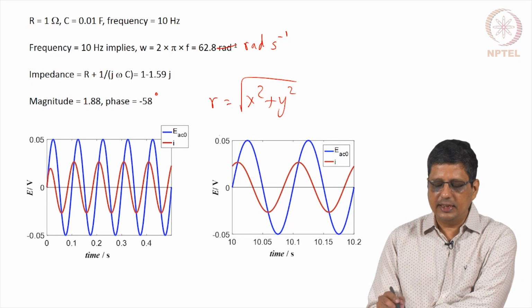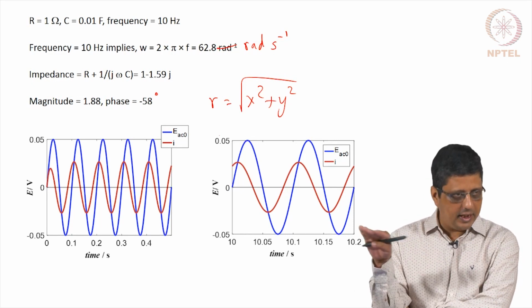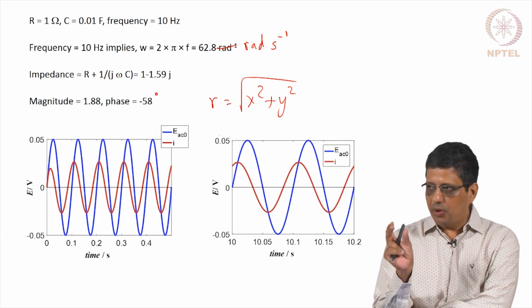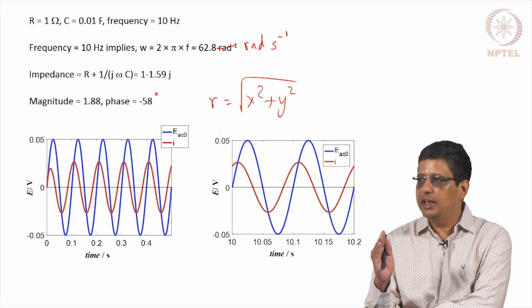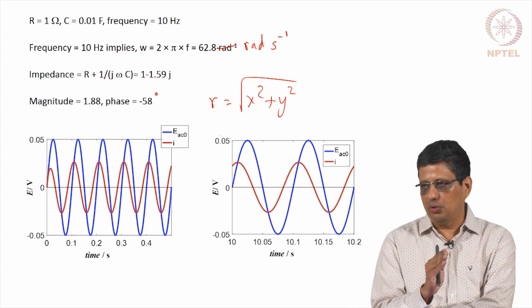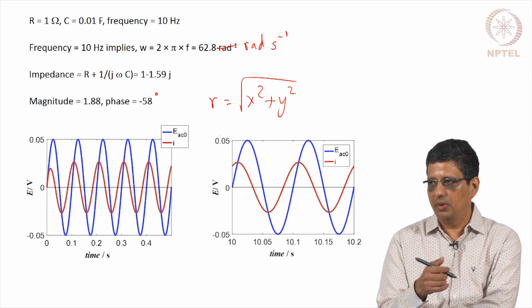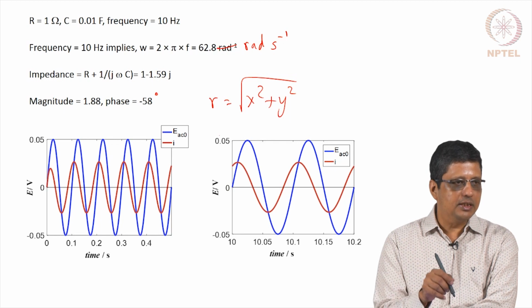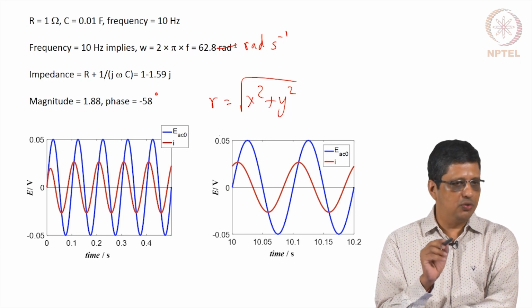So, this type of result is called steady periodic. That means it is not steady value, it is periodic, for one oscillation to next oscillation it is not different. So, after some time it achieves steady periodicity. In the beginning there is some transient also, later the transient becomes negligible. That information does not come by looking at the complex plane notation and adding r plus 1 by j omega c.